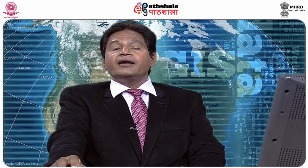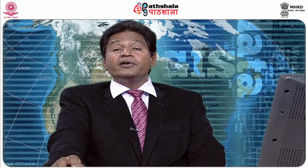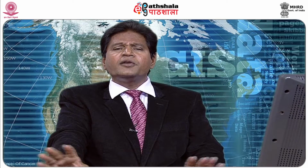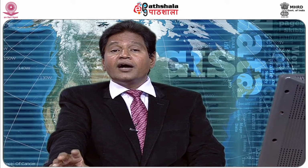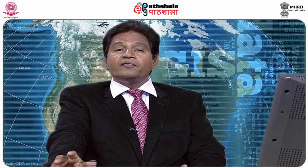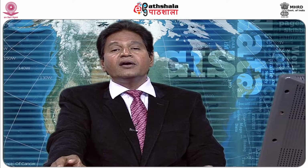From survey, I get the inputs such as the owner and the extent of the land he is owning there, and finally, using GIS, I will be able to integrate both of them and get the detail in a very good fashion, and it will be as accurate as possible. Because again, please bear in mind, GIS will not be in a position to give you accurate results. It all depends on your input data. As always I say, garbage in is garbage out. So, the better the input data, the better will be the output.